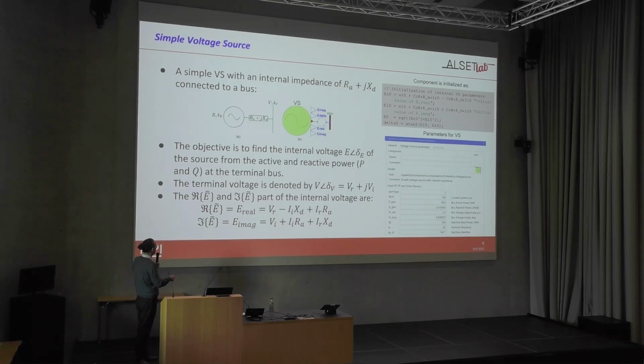So this is how I did this, right? The terminal voltage is going to be given by this V, angle delta V, and is a complex variable. To calculate the terminal voltage here, you just do Kirchhoff's current law, and you find the real and imaginary expressions. And so these expressions, during initialization, you can actually type the initial equations for,